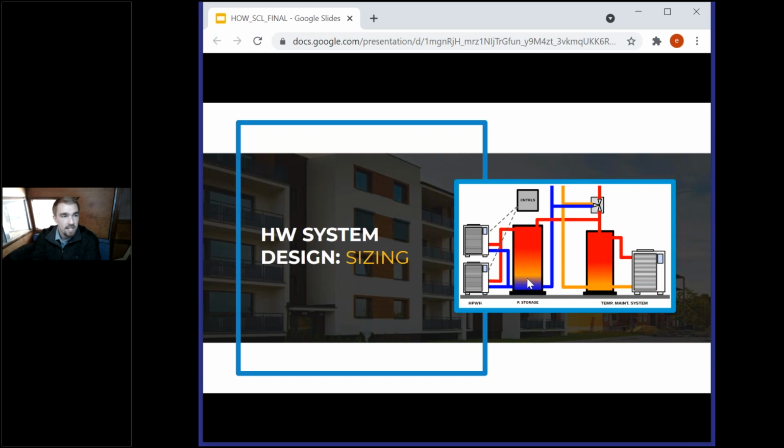Talking about sizing, it's really important to take a little extra time on this versus how you might conventionally size a typical gas water heating system as a designer, because we've talked about the need for more storage to handle these peak loads, while the heat pump can be sized much smaller than a boiler in a properly sized system. That's going to bring down your overall project cost, because the price per BTU on these heat pumps makes them cost a lot more if you're sizing for that peak load.